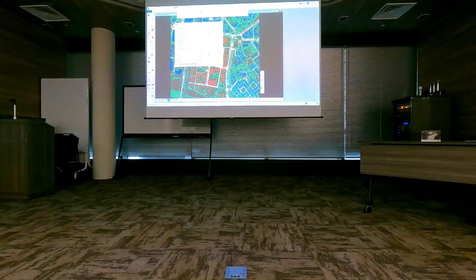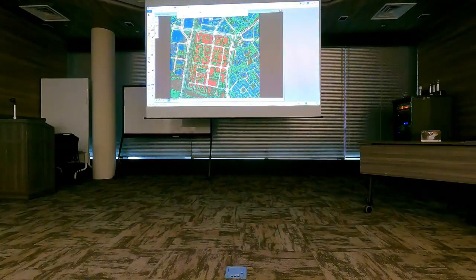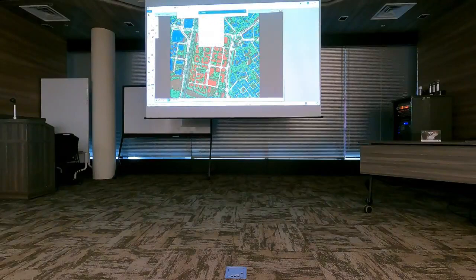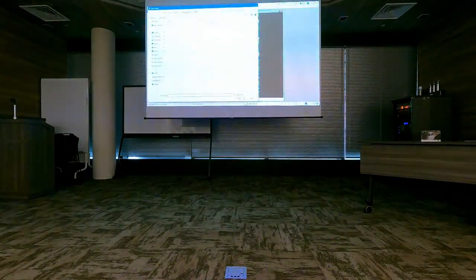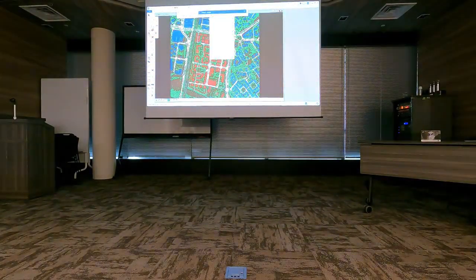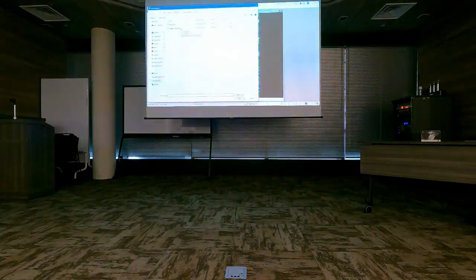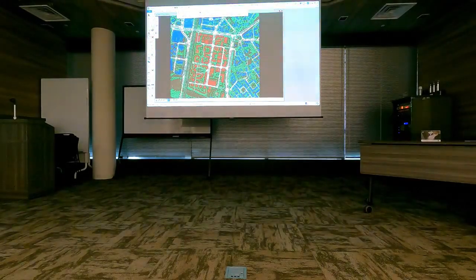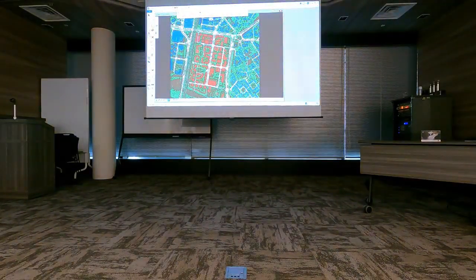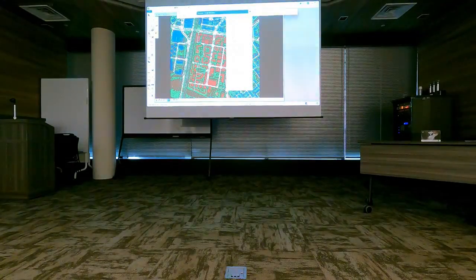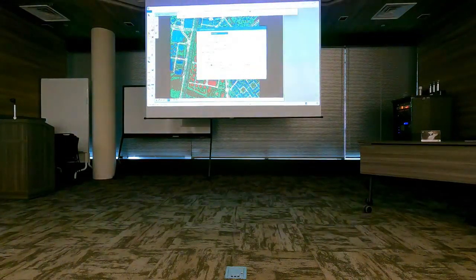And I need to have TerraPhoto running in addition to TerraScan. I need to have a mission open. I need to have an image list. And I must have done extract color from images. And I must store image numbers.